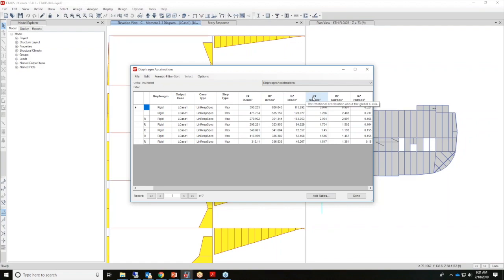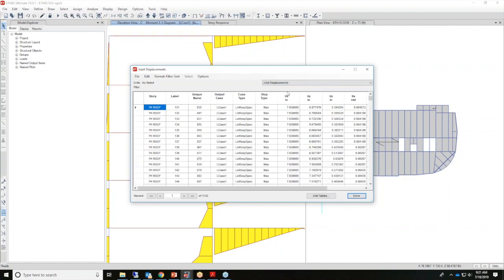So it's also important in taking a look at joint displacements. Now you'll see here, when you're looking at displacements, all the values are positive. This is due to how the model results are combined. All deflection values are going to be positive for response spectrum.